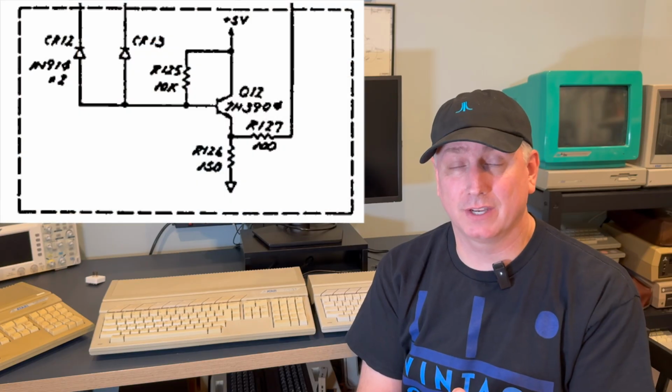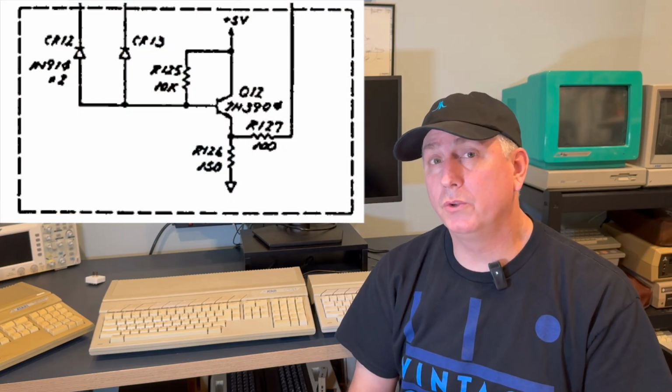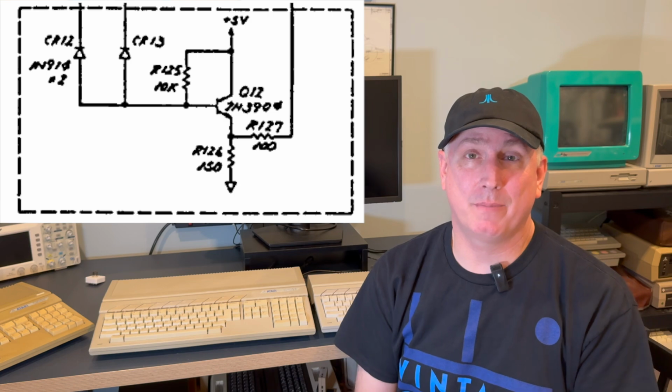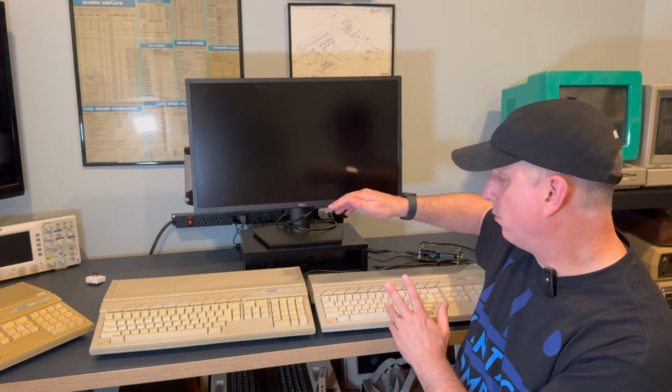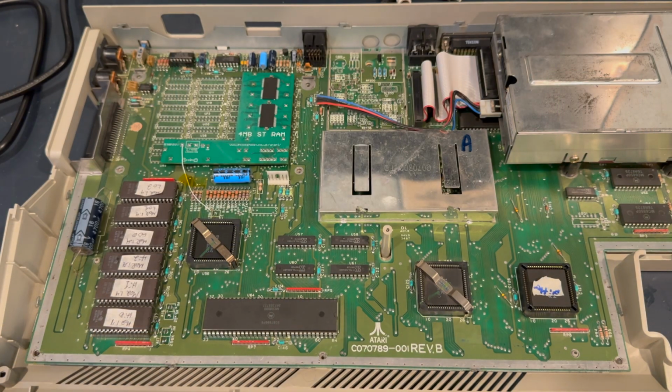There is circuitry that can be added to many Atari STs that can simply add the composite signal, but many of the older Atari STs don't have that composite sync signal. And as such, like this original Atari 520 ST from 1985, it does not have it. And so with the SCART, you're not going to get a good video output, or you're not going to get any video output.